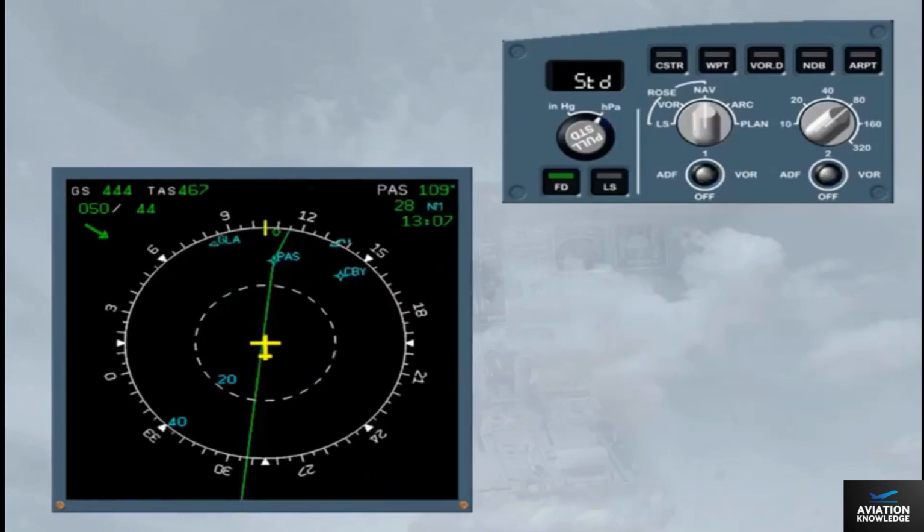A map view of the area surrounding the aircraft is now displayed. On the EFIS control panel, the range selector is set at 80 nautical miles. It is the distance from the bottom to the top of the compass rose. The green line represents the flight plan. It will be studied in the A320 Auto Flight chapter.